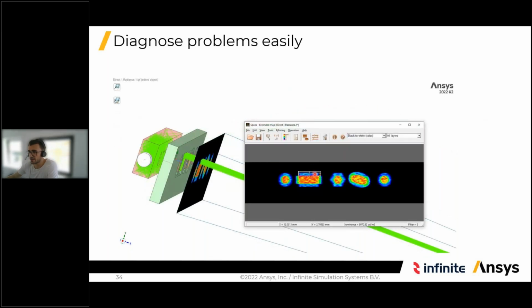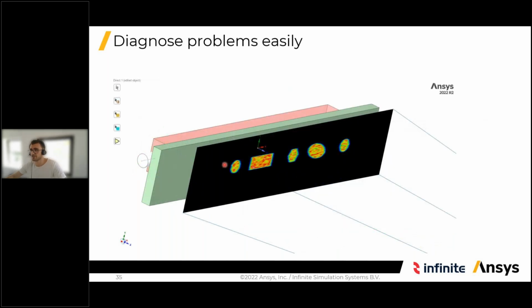In my sensor, I can select the problem areas, as you can see here with this rectangle, and then the software will visualize all the rays that end up there. And now I can see where the problem comes from. Some of the light rays are reflected at these chamfers here, and then they end up at the sensor. So by redesigning this dashboard, maybe by removing the chamfers or by adding some coating to it, I can get rid of these unwanted reflections. So it's very easy to do.